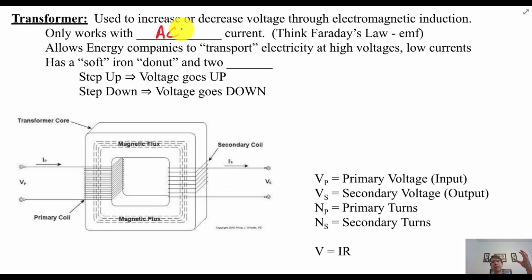But you can't have 10,000 volts in your outlets. So when it gets to the cities, or to the corner of your street, even before that, they step it down. They transport it at like, I don't know, 100,000 volts. They have other stations in cities that bring it down to like 10,000 volts. And then at the corner of your street, and sometimes this happens in an electrical storm, you'll say, oh, the transformer at the end of your block got hit. That is a transformer stepping it down, that's the terminology they use, from say 10,000 volts to 120 volts before it goes in your house. Because 10,000 volts could more easily kill you than 120 volts, which still could kill you, especially if you're standing by water.